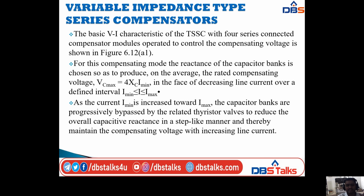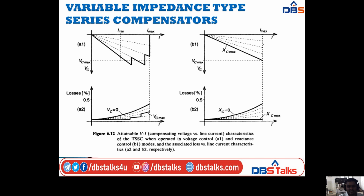In the face of decreasing line current over a defined interval, I is between I minimum and I maximum, the line current being between minimum current and maximum current. As the current increases from I minimum towards I maximum, the capacitor banks are progressively bypassed by the related thyristor valve to reduce the overall capacitor reactance in a step-like manner, thereby maintaining the compensating voltage with increasing line current. This is the explanation for the A1 diagram.